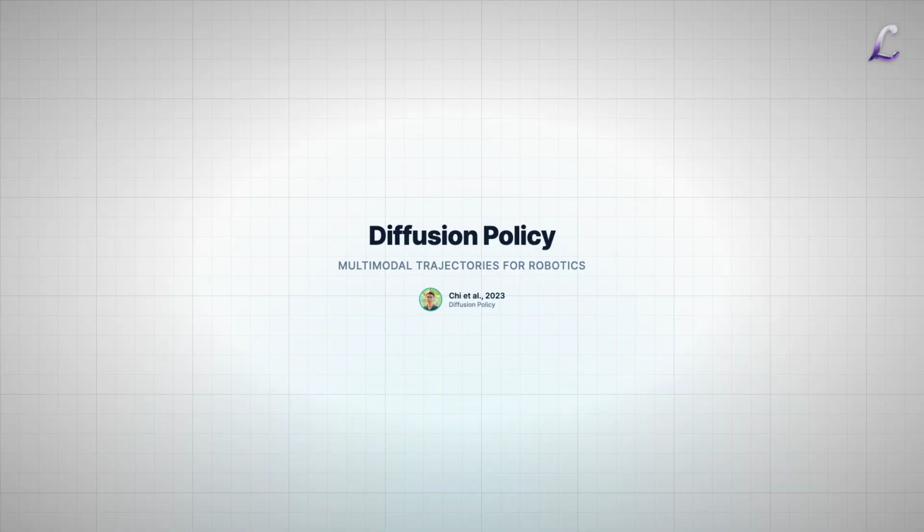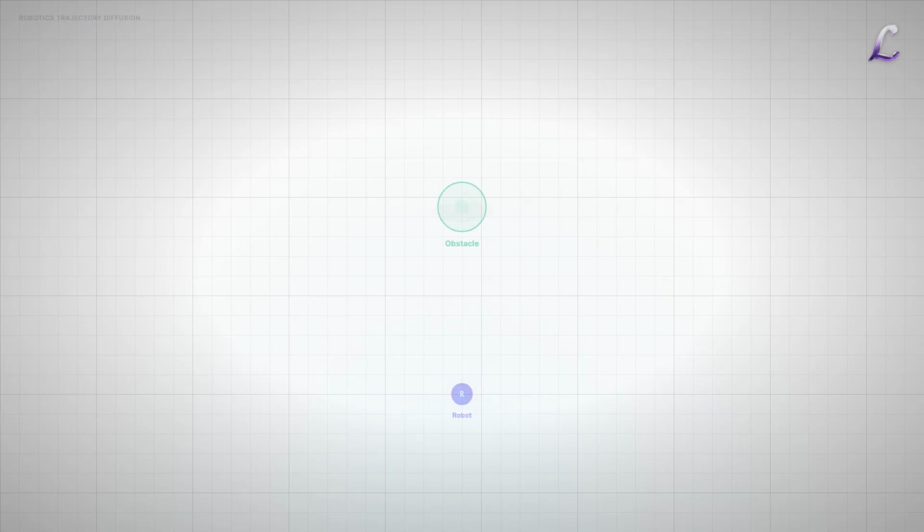Now, let's move to robotics. Traditional reinforcement learning policies are often unimodal. They try to output the single average best action. But suppose a robot needs to go around a tree. It can go left or right. The average of left and right is straight ahead, crashing directly into the tree. Diffusion models solve this naturally because they model distributions, not point estimates.